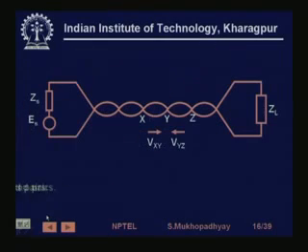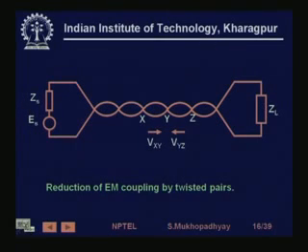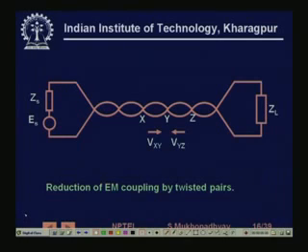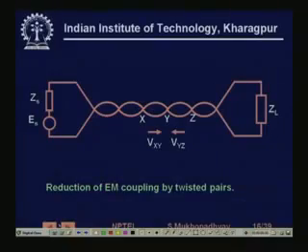So before we discuss that, the first thing that you have to do is see that very little flux is linked from other sources. So flux linkage, if you want to reduce, you have to reduce the area of the loop. You have to keep the coils close, and we know that if we twist the coil, so you have a twisted pair of wires, then, for example, you see this is one leg xy and this is another leg yz of the same coil.